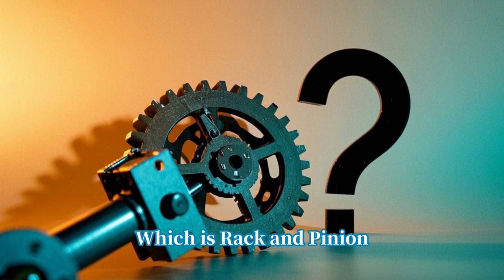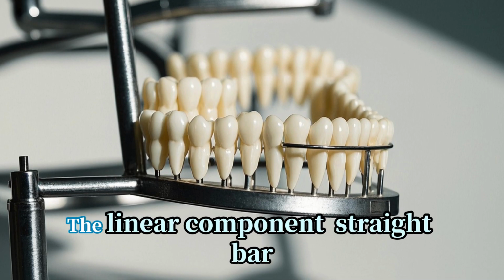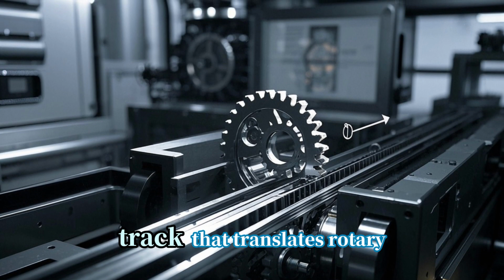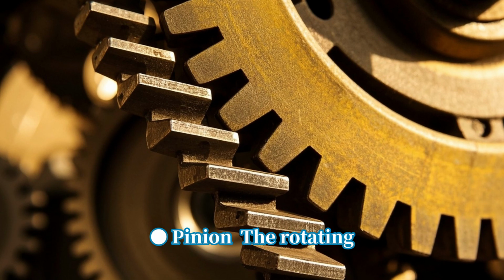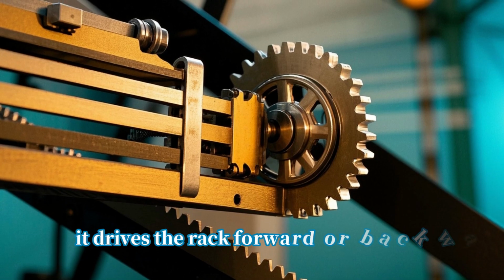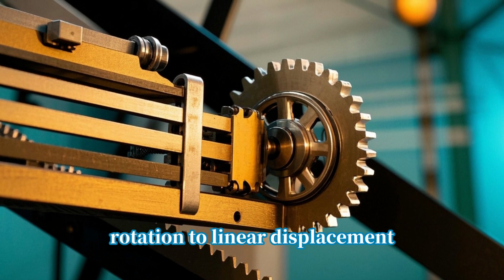What is rack and pinion? In a rack and pinion system, the rack is the linear component, a straight bar with teeth running along its length. It acts as a guiding track that translates rotary motion into straight line movement. The pinion is the rotating gear with teeth that mesh directly with the rack. When spun, it drives the rack forward or backward, effectively converting rotation to linear displacement.